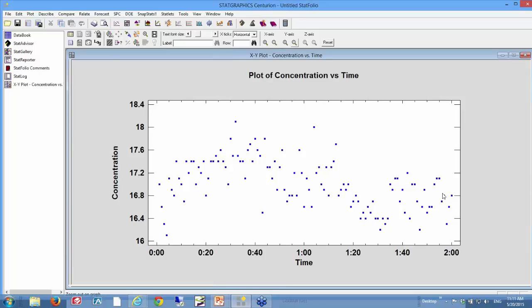Now, that doesn't necessarily mean that that's an out-of-control process. Okay? There are dynamic processes that have serial correlation between successive observations but are in fact stationary. This process may well have, in the long term, a constant mean and a constant standard deviation. However, the dynamics of the process are such that if you look at it, you do see some natural inherent swings around the process mean.